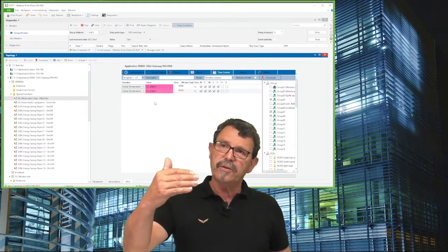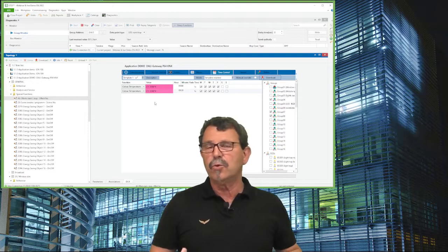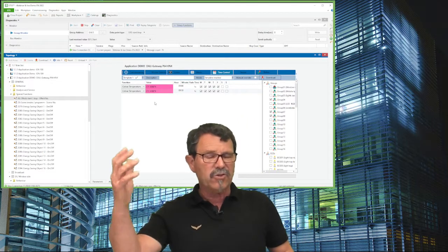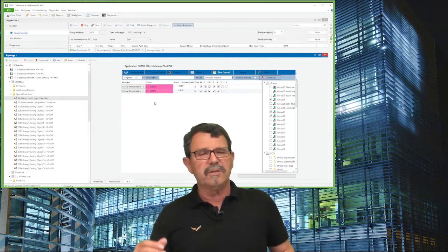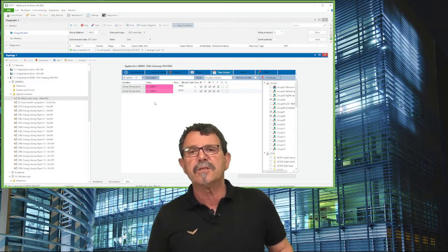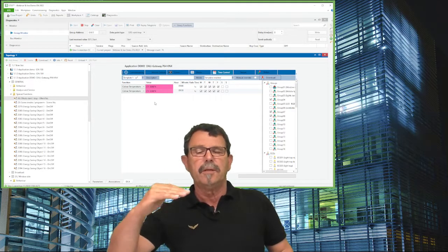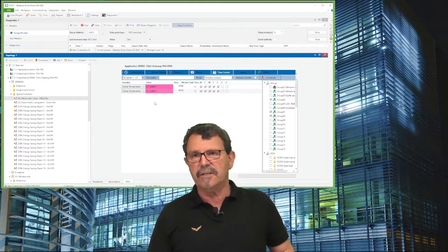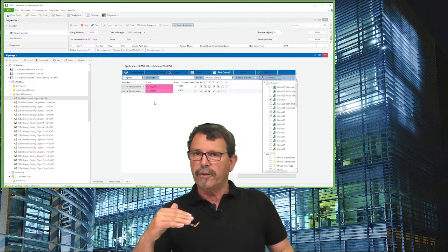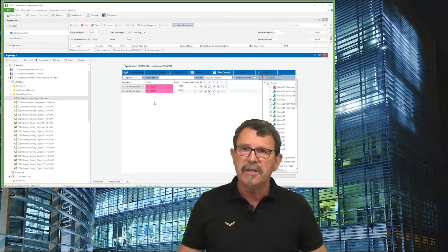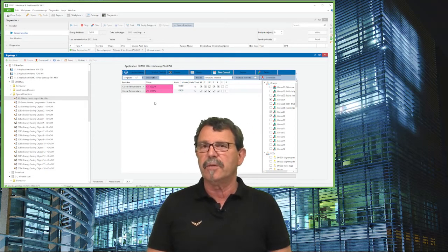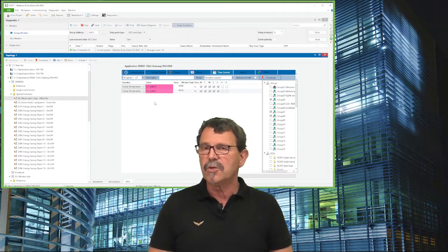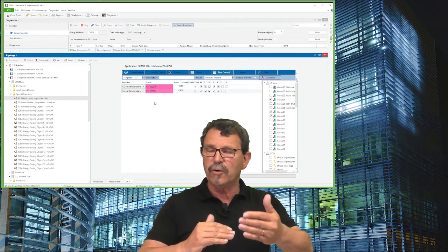And so you go up, for instance, from 3000 K to, let's say, noontime approximately, then you reach 6000 K, so like the natural daylight, and approximately 2 p.m. or so. Then you start to modify, to dim down again, or to change finally the color temperature down to more the warmer lights in the reasonable steps, which you can choose, which you can set up. You set up the color temperature, you set it up as well. So the time when it shall happen, the change from to.